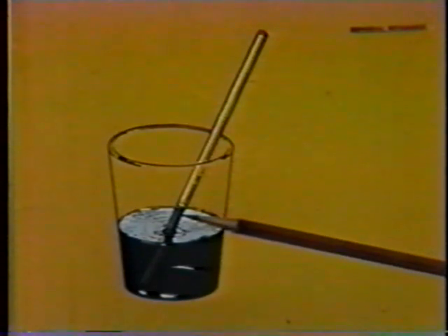Liquid penetrant testing uses an oily liquid plus capillary action to detect discontinuities. The oily liquid containing a visible color or fluorescent dye is applied to the clean, dry surface of the test specimen and permitted to seek out possible discontinuities. After a sufficient time interval for the penetrant to enter discontinuities, dwell time, the surface film is removed.